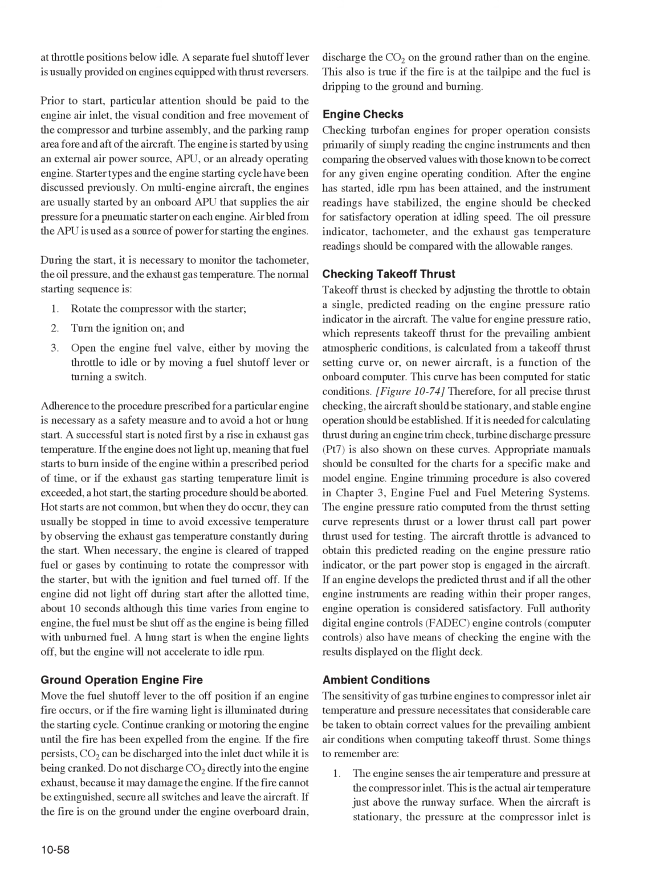During the start, it is necessary to monitor the tachometer, the oil pressure, and the exhaust gas temperature. The normal starting sequence is: 1. Rotate the compressor with the starter, 2. Turn the ignition on, and 3. Open the engine fuel valve, either by moving the throttle to idle or by moving a fuel shutoff lever or turning a switch. Adherence to the procedure prescribed for a particular engine is necessary as a safety measure and to avoid a hot or hung start.